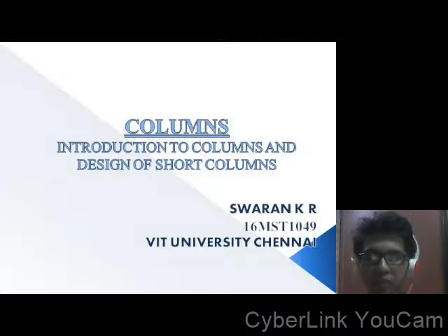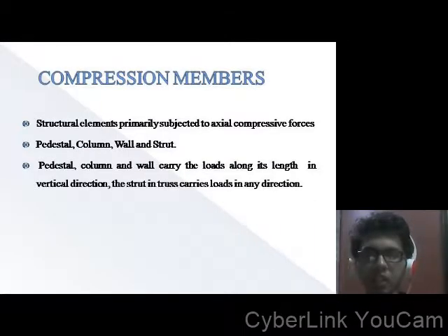This session we will be dealing with columns, that is, we will be mainly concentrating on the introduction to columns and design of short columns. Before moving into the column system, we'll see what a compression member is. We all know that a column is an example of a compression member. A compression member can be defined as a structural element which is primarily subjected to axial compressive forces.